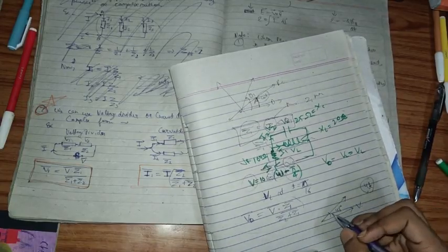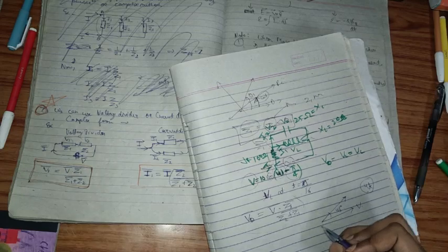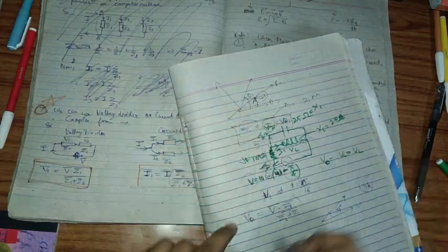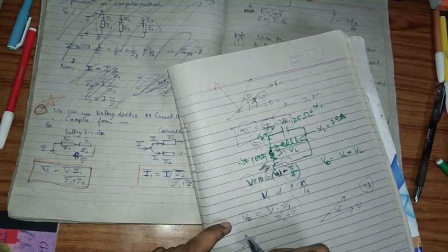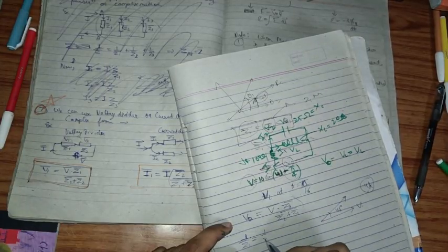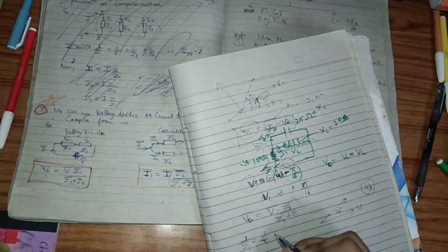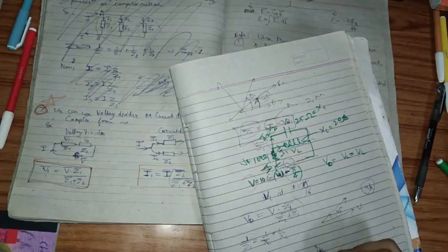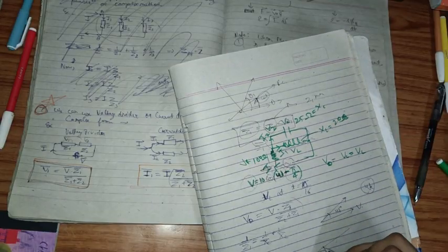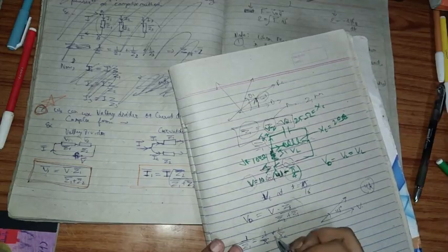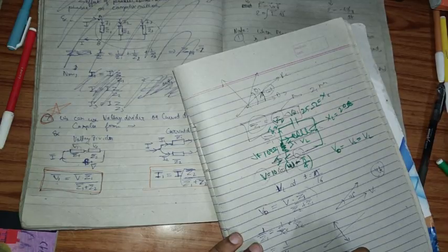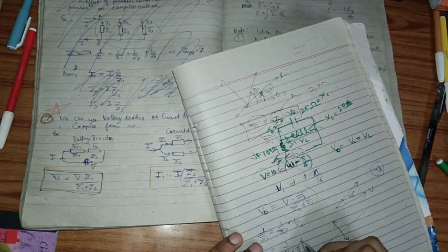In this case, with this reference frame, we know that XL is above and XC is behind. So this can be written as 1 upon XC at minus π/2 angle plus 1 upon XL at plus π/2 angle, and that is giving me Z1. The XC and XL values are known. This is 20 and this is 25. So this angle goes above and becomes plus π/2. This angle goes below and becomes minus π/2.